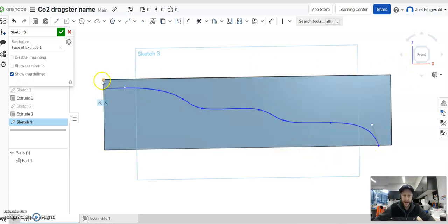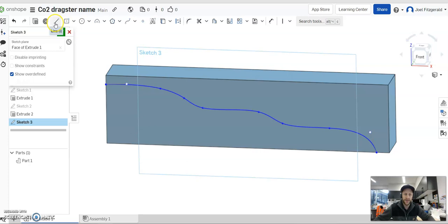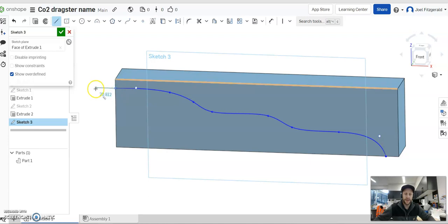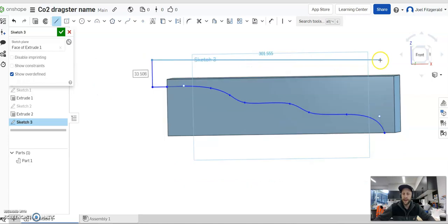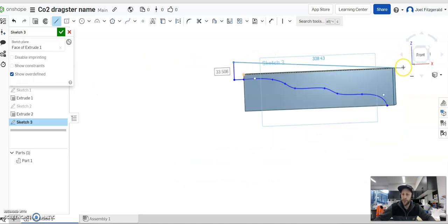Now, in order to cut out that profile, I want to get rid of that. I must make sure that this becomes a closed loop. I'll show you what I mean by that. I'm going to use the line tool to build my loop, and I'm actually going to overbuild it. I'm going to draw a line out from here, horizontal, and come up out here like this, just to make sure that this is going to pick up all my detail.